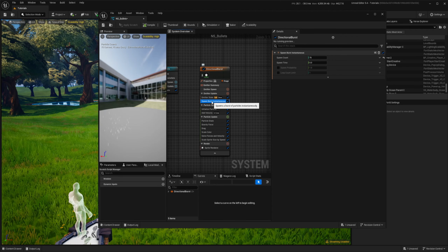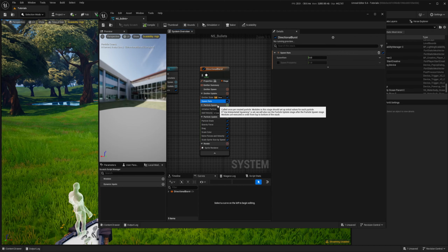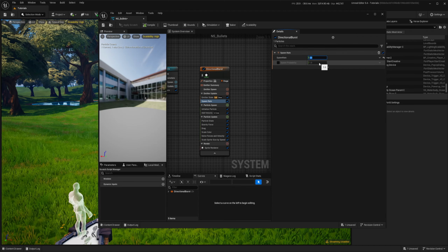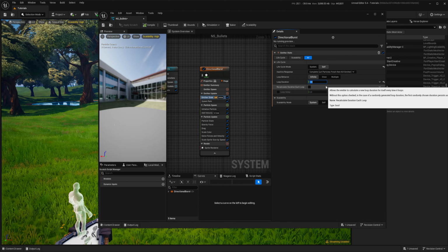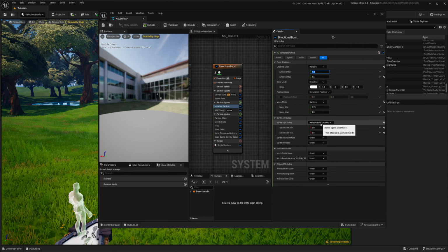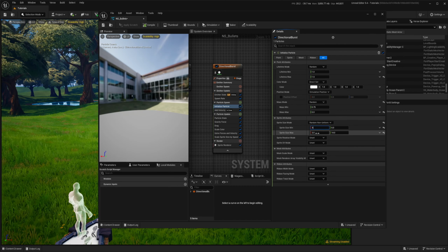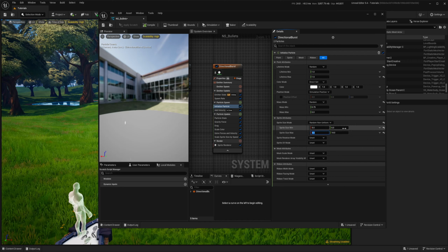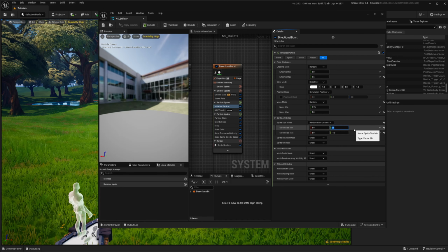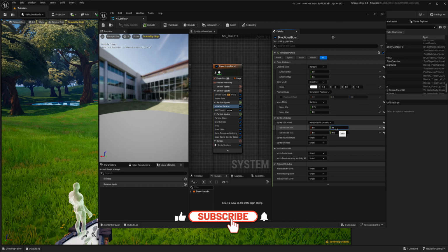So first of all, I don't need burst. I will pick spawn rate. Choose maybe like 2. And maybe like 0.2. Right, so you see like now in this small window. Now in random non-uniform scale, I will keep maybe a little bit larger so we can see better, maybe 5, but then scale it like 50 or so. Yeah, maybe like that, maybe 30.